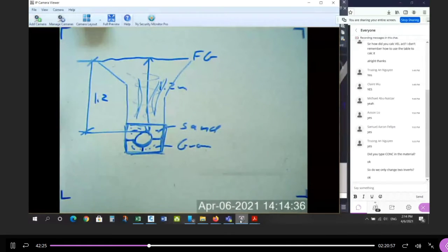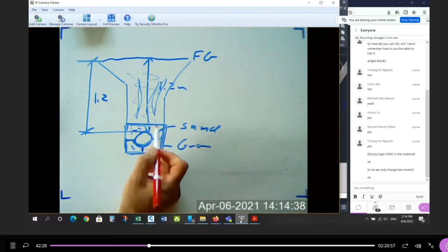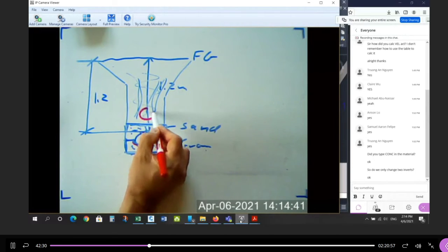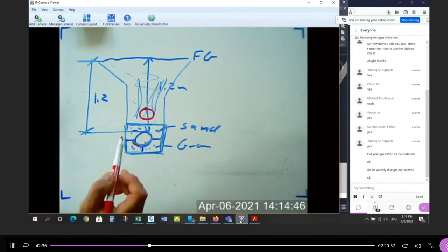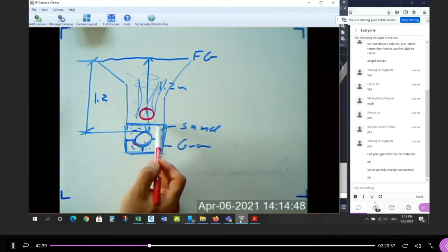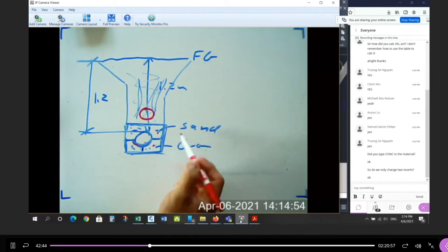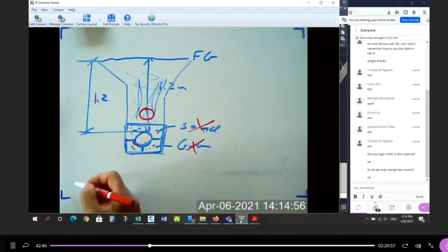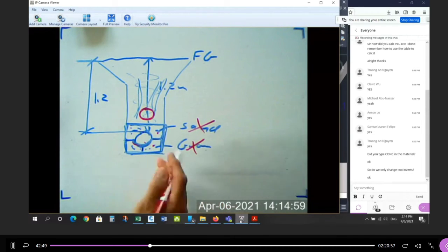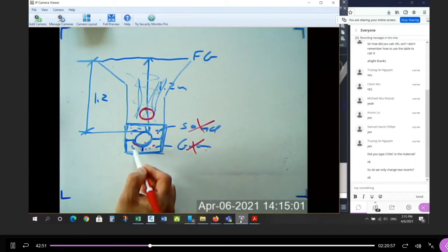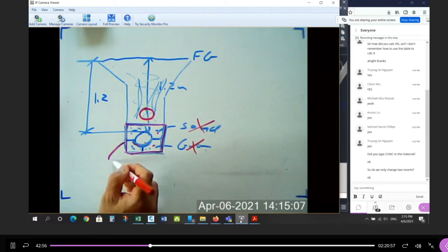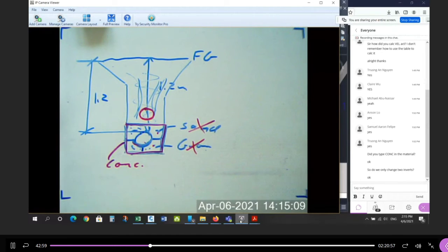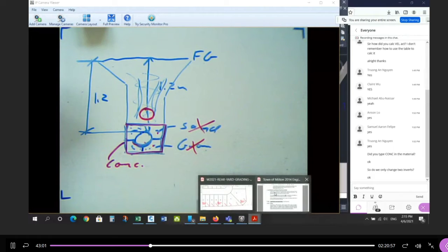Now, when we compromise that, here's what happens. I'm going to take this and shift it up here. Now I no longer have cover. So what do we do? Usually, not always, but usually for the rear lot catch basin lead, instead of granular and sand, which is a typical street sewer, when you go between two houses, they don't want you to use granular and they don't want you to use sand. They want to concrete encase the pipe, make it all concrete. That's another option, and I believe that's covered in the standard.